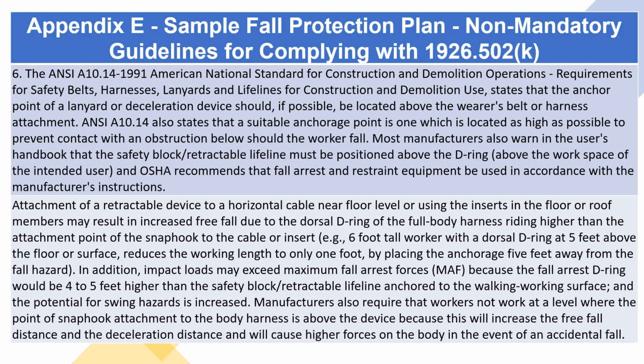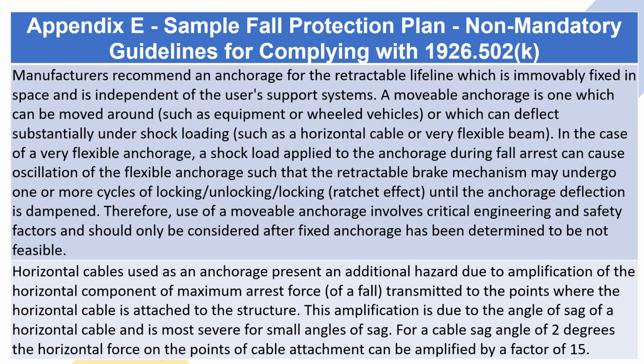is increased. Manufacturers also require that workers not work at a level where the point of snap hook attachment to the body harness is above the device, because this will increase the free fall distance and the deceleration distance and will cause higher forces on the body in the event of an accidental fall. Manufacturers recommend an anchorage for the retractable lifeline which is immovably fixed in space and is independent of the user's